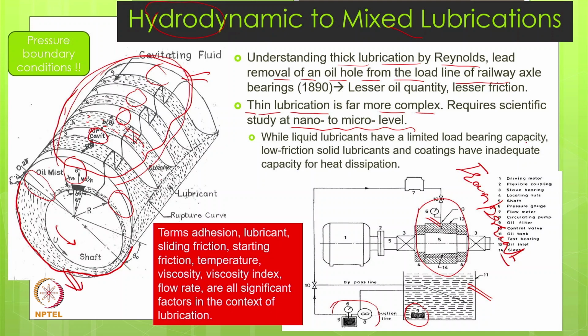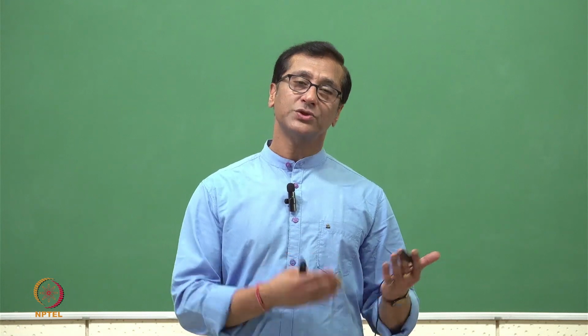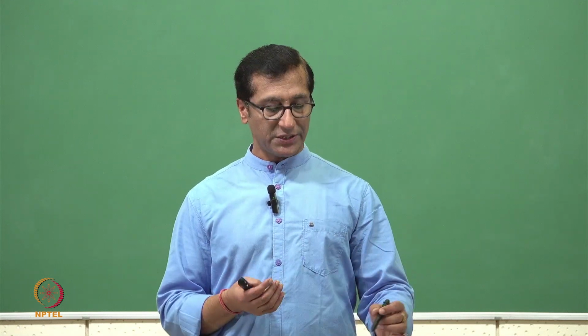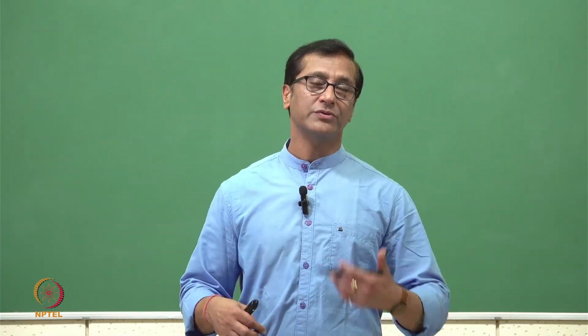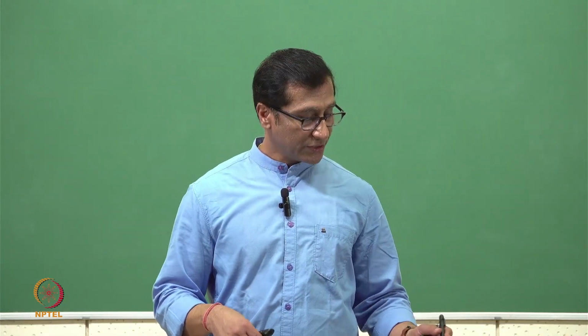And we say that liquid lubricant has some limitation: its load carrying capacity is slightly lesser compared to solid lubricant. However, solid lubricant and coating have one of the major issues, that they cannot dissipate the heat. So there are some advantages with a liquid lubricant and some advantages with a solid lubricant, and that's why we say better we go ahead with mixed lubrication. We connect both. We want liquid, we want solid, or maybe boundary additives, so overall results are in our favor, or maybe overall favorable to the tribology society.